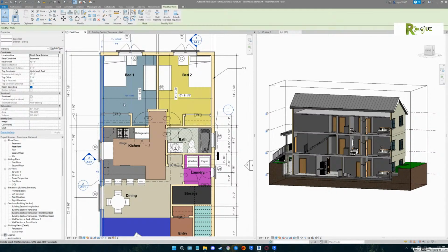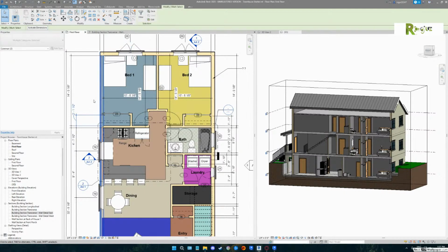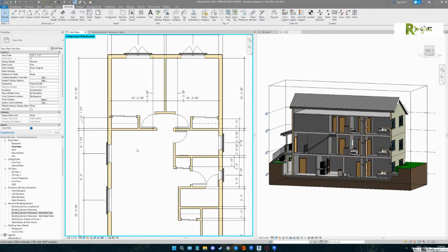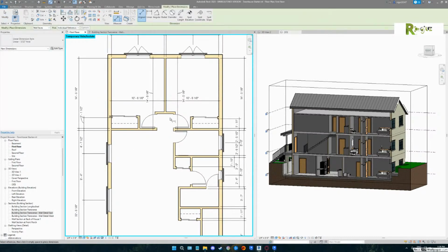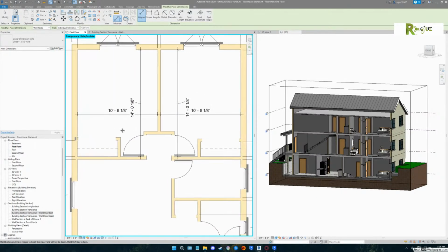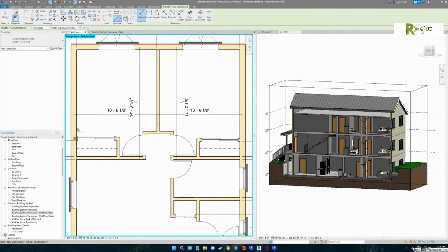pick one of your dimensions, you use the control and select the dimension and pick a door and pick a window. Now isolate category with your sunglasses. Now you could dimension. Okay, that makes sense. Now you're not going to accidentally grab something that you're not meaning to grab. Now, if you're going to try to go across there, yep, hit the first edge of the outside wall.